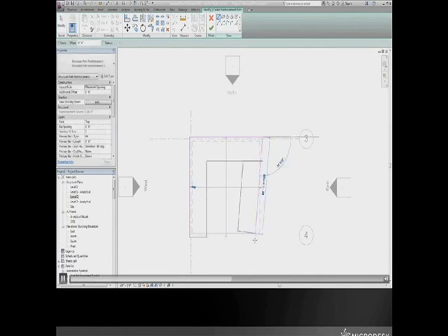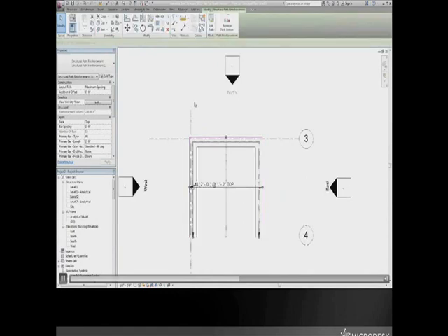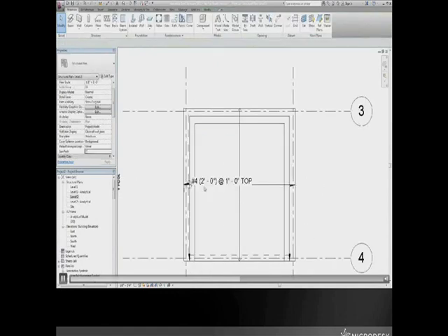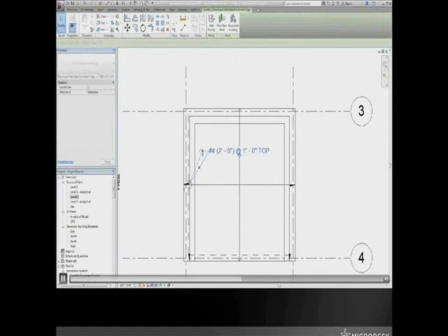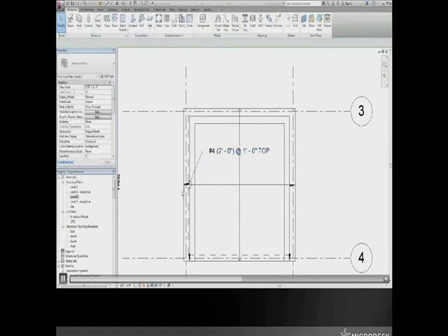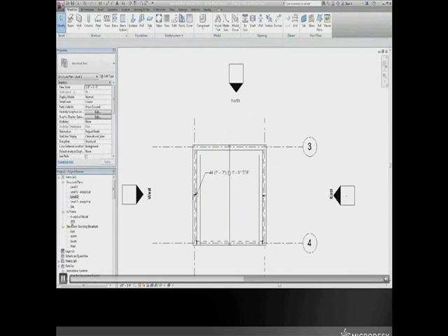Finishing drawing in this final side. I'm just going to do 3 sides for now so we could get an idea here and see it better in 3D. And now I'm changing the length that will be doweled into the slab itself. I'm pressing the check mark. The path reinforcement has been created, tagged, and now we could go to a 3D view and see what we did so far.